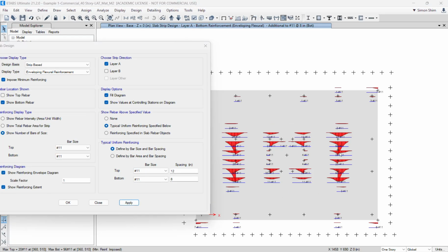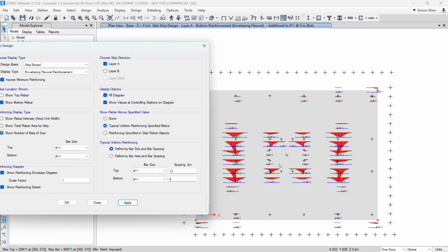All right, so the bending, okay, rebar is because of the bending moment underneath. You could double check all the bending moment under the wall, right? And that actually causes the amount of bending moment, and then the required amount of bottom bar. So you need to do some iterative exercise. If you think this is a reasonable bar and additional bar, you can sum them up and redistribute it along the width of the wall.